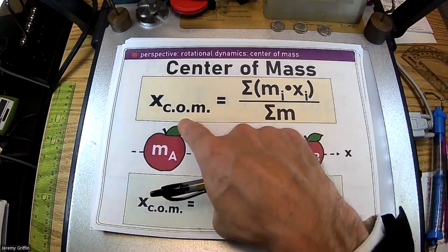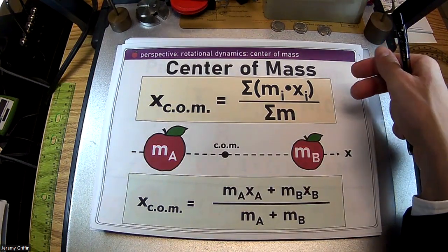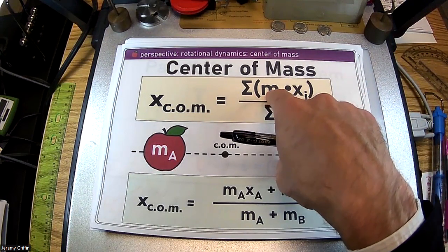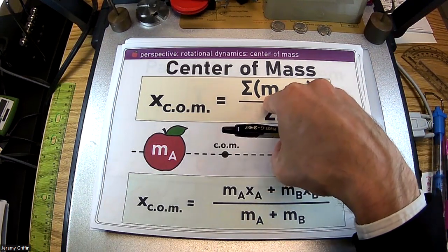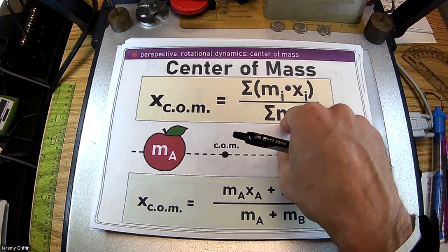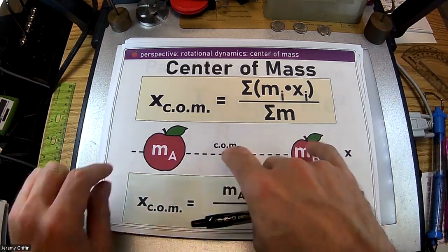In general, a way you can get the center of mass is you take a weighted average of all the mass bits. Say you break something into a billion parts. You take each individual mass bit times its location, you add everything up and then divide by the sum of the total mass. That gives you an average location of the mass, which is the center of mass. So for example, what if I got 2 point masses?